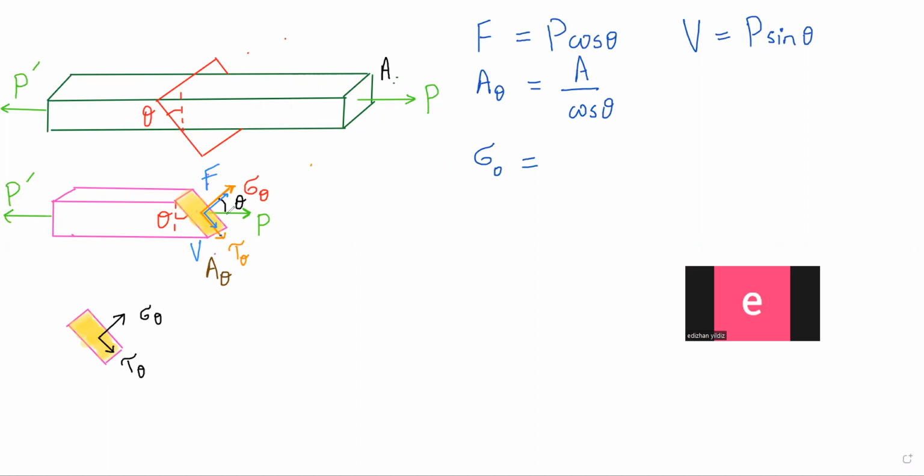Okay, thank you. This load can be divided into two components. So you can see this green arrow. I have divided it into two components. One is this capital F and one is this V. I think I have done overall a horrible job of making this, because I don't think if you add them, you get a P. So I think this arrow should be a little longer, right? Anyways, we will correct this. The whole point is that this F plus V will give me this P. So anyone who wants to tell us which force is the normal one and which one is the shear one? The V is the shear one that is along the section and F is the normal force, right?